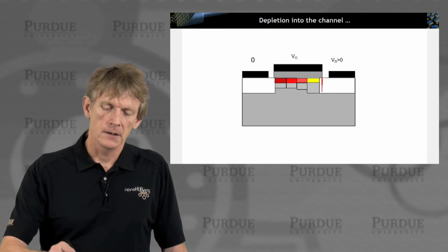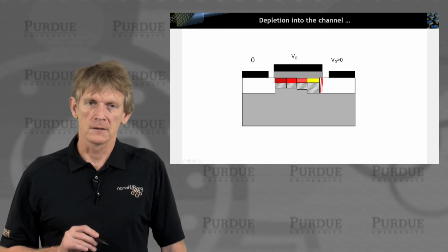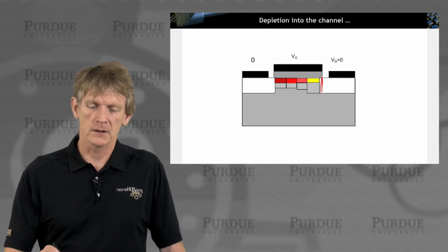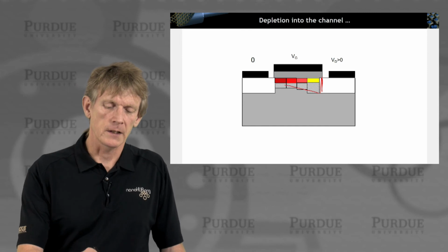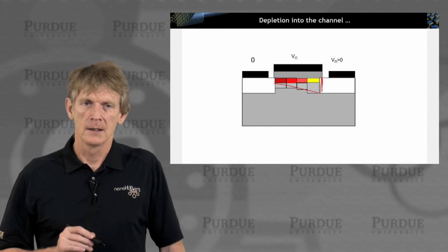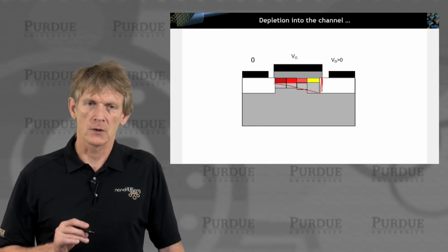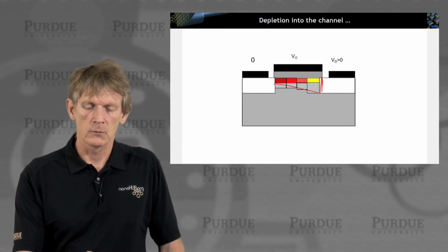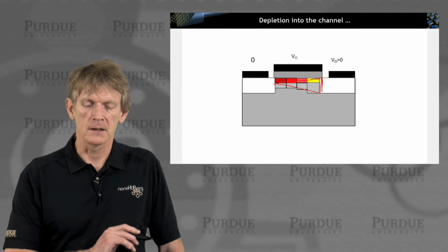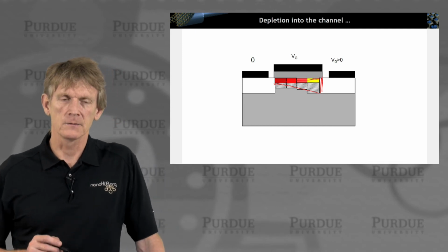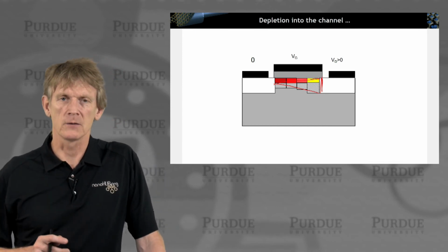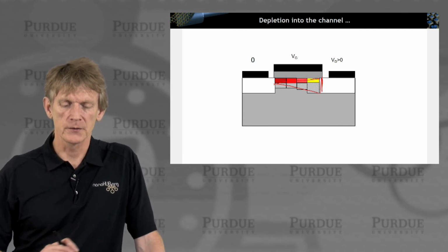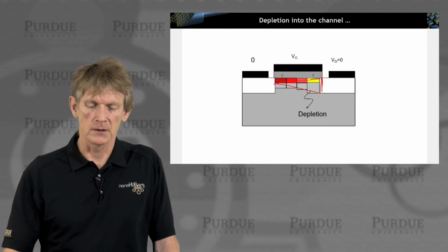The effect of the drain voltage modifies the depletion significantly in this direction, because you have a strong effect of exposing the acceptors, and it's somewhat counteracted by the channel getting narrower and narrower due to the interaction of the gate potential with the drain potential. Okay? So you have to account for those different charge distributions. So this is the depletion.